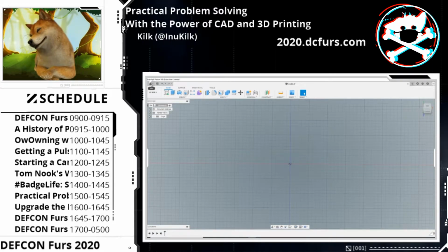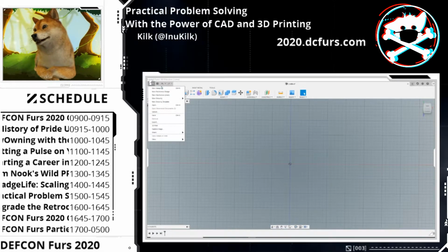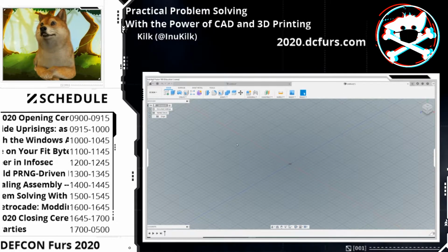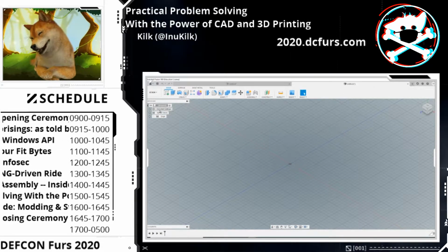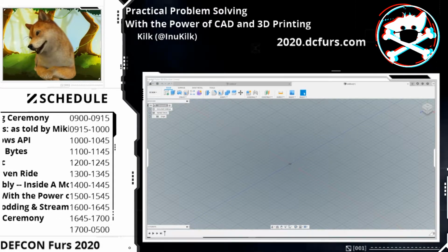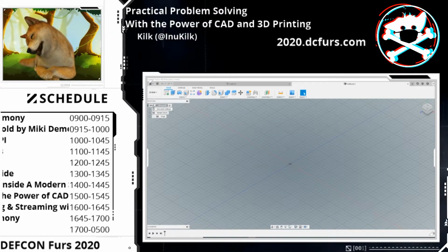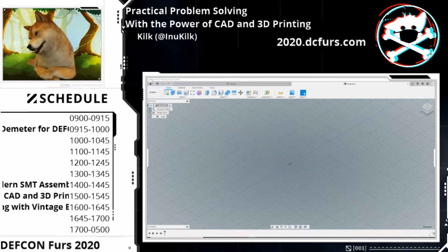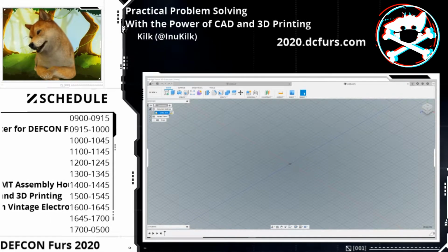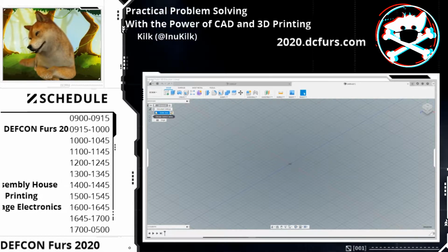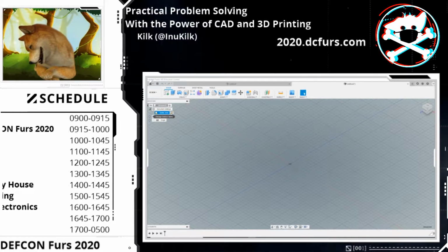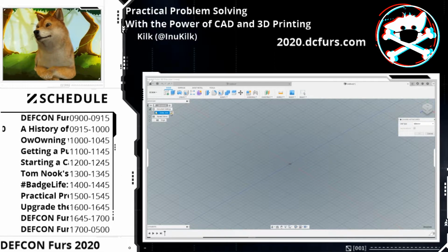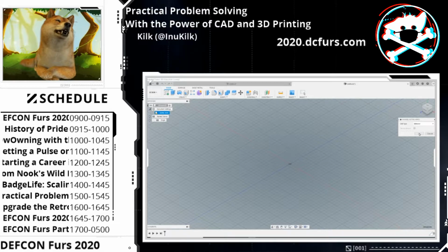So to make a new file, if you want to make a new design, you hit New Design, and there we go. We have a new window for a new design. Another thing is right here where the browser is. You drop it down. Usually, it's important that your document settings are in millimeters. The metric system rules. You want to hit the icon right here next to the units. Millimeters, or it's usually going to be in inches. That's what it starts out as, and you want to change it to millimeters.